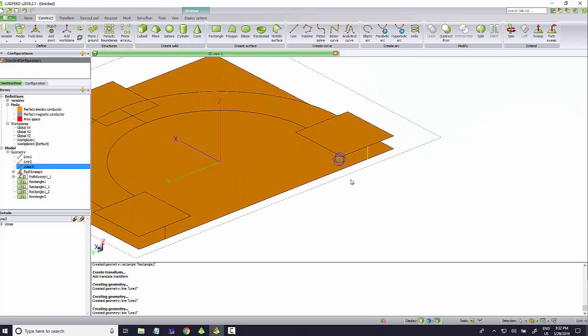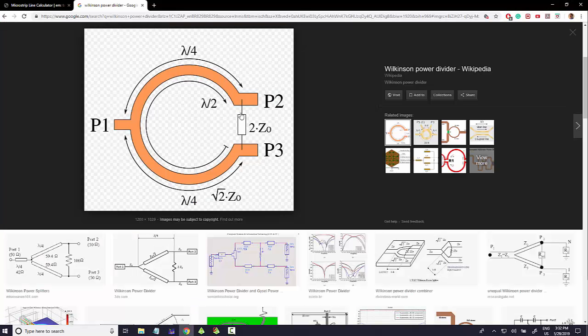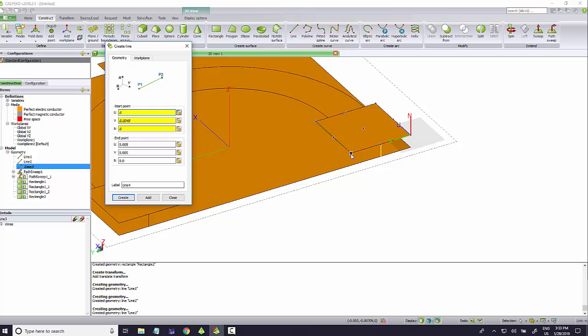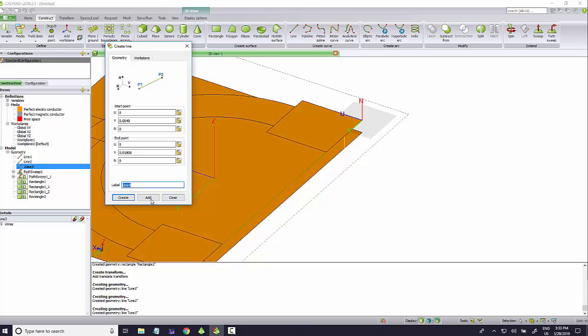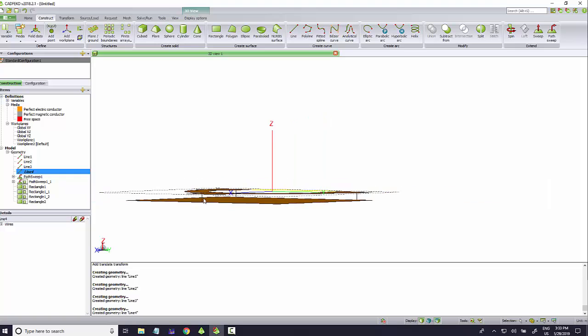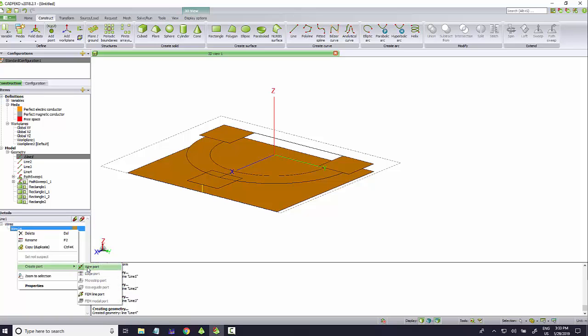And then we have to think about our resistor. How can we model a 100 ohm resistor here? There is a very easy way to do it in FEKO. We do a line here again, Control Shift, for instance, from here to Control Shift here. Design another line, and now we assign these lines to ports. We select this line here, wire 14, right click, create port, wire port.